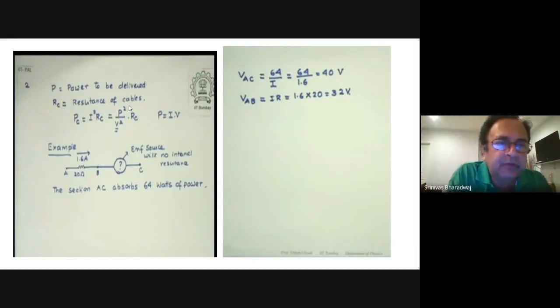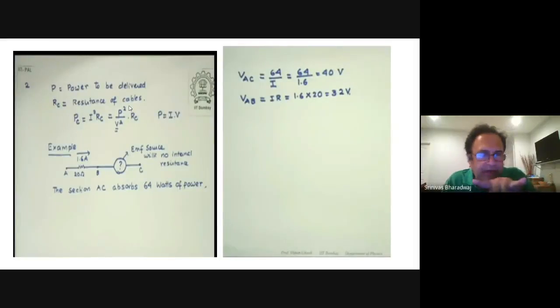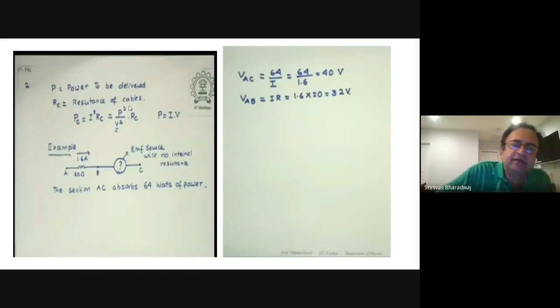Okay. So we are now discussing power and the meters that you have in an electrical circuit, right? Power is V square by R, I square R, V times I. Three different measures, and V is equal to IR, which is Ohm's law, right? Now the voltage between any 2 points is measured by this device called a voltmeter. Typically, you expect this voltmeter to have no resistance, to have an open circuit, but most often it will have a small resistance, and it will change the value of the current in the circuit itself during the time that you measure it. Okay.